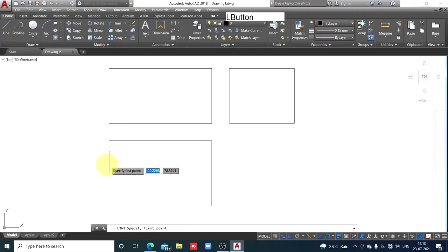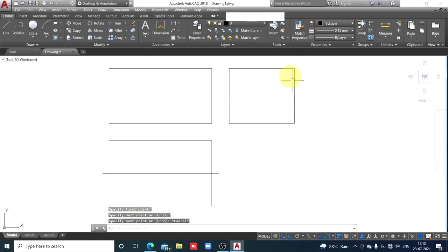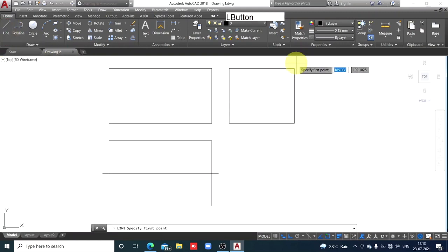So line, here is the midpoint, track the midpoint, slightly outside the rectangle, click it, and then here you click it. Escape. Here also, in the side view, this is the front side, this is the back side. Front side and back side are similar, and therefore I'll draw an axis of symmetry in the side view.